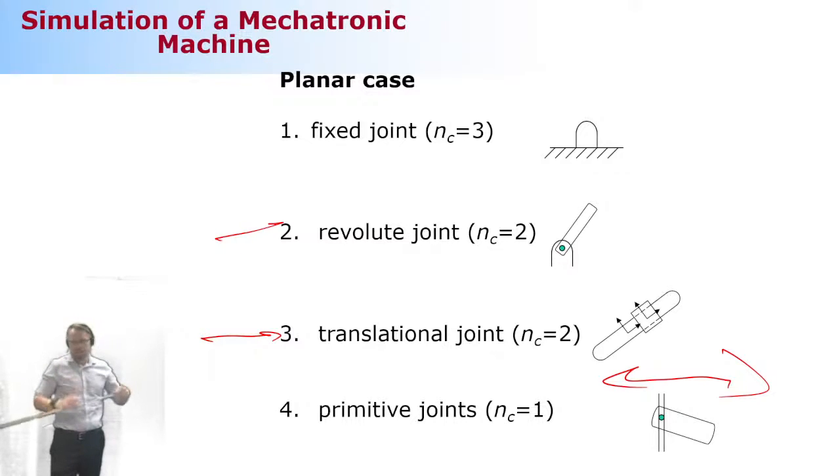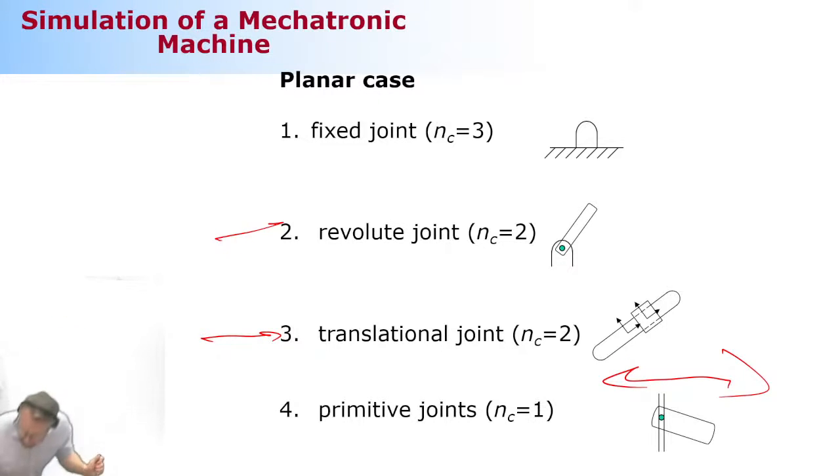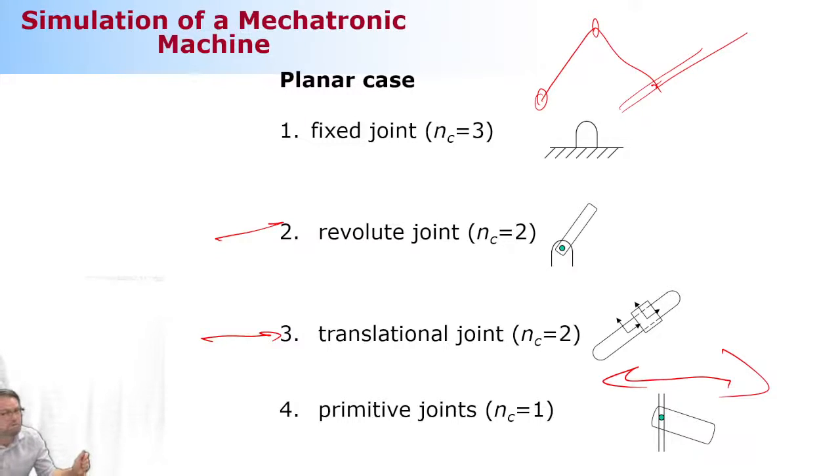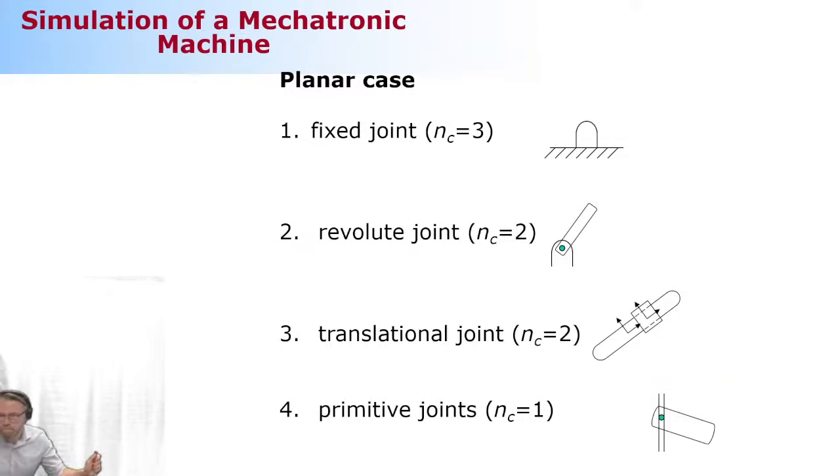Okay, if you have a crankshaft like this, revolute joint, primitive joint like this. The primitive joint could be at this angle. I have two moving bodies, so I need a total of 6 generalized coordinates. Then 6 minus 2 multiplied by 2 joints, and then one primitive joint because of this. So the degrees of freedom is 1. All right, so let's move on.